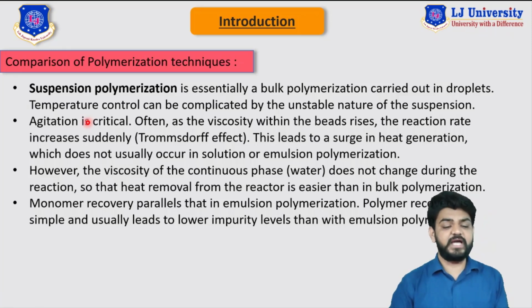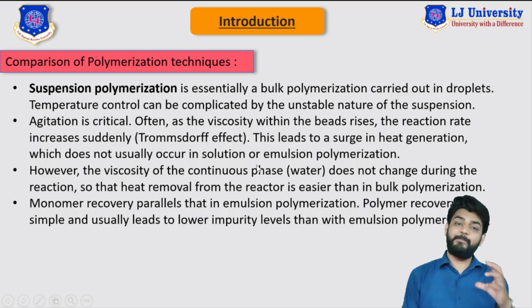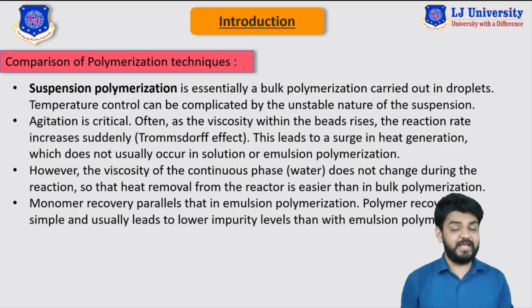The agitation is again very critical with the suspension polymerization. As the viscosity within beads increases, the reaction rate increases suddenly, and this leads to a surge in heat generation, which does not usually occur in solution or emulsion polymerization. So now you can compare suspension polymerization with emulsion and solution polymerization, as the reaction rate is very high in this technique, which occasionally leads to a sudden increment in the reaction heat.